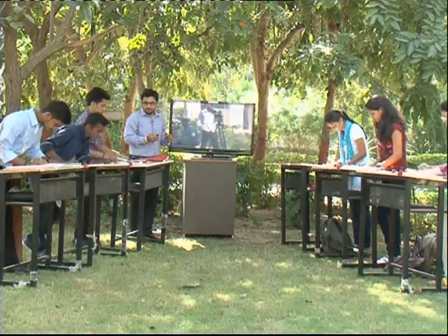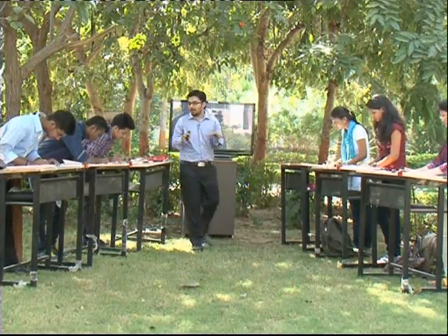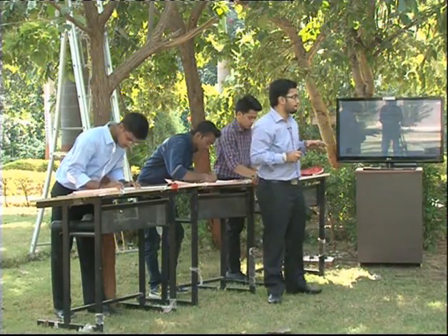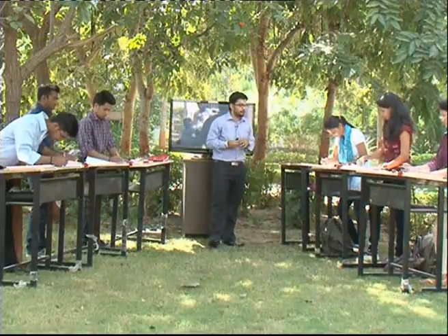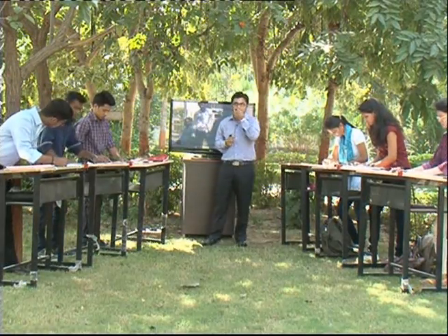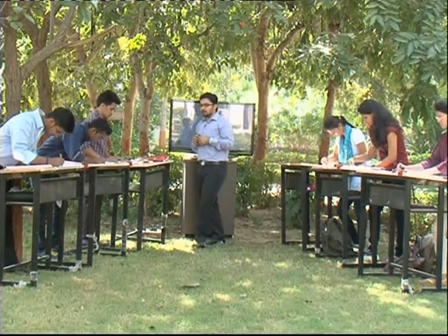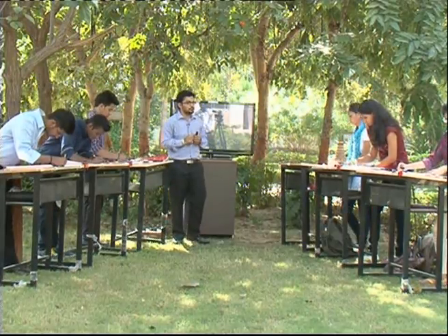So moving on, first of all draw a major axis exactly as per the measurement that is given to you. We will be drawing 4 curves on the sheet. So I hope you have already divided the sheet into 4 parts. Draw a straight vertical line. The line can be drawn on the sheet with the use of a drafter.